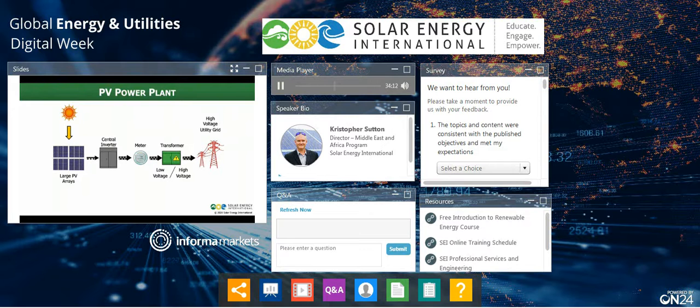And so then we're just putting megawatts worth of solar to match the inverter input. Going out of the inverter, AC synchronized to the grid. In the same way, it does the auto synchronization because it's not like a motor generator. It's a solid state piece of electronics. And so it automatically synchronizes with the grid. It doesn't make its own voltage. It does the same thing. It synchronizes with an external voltage.